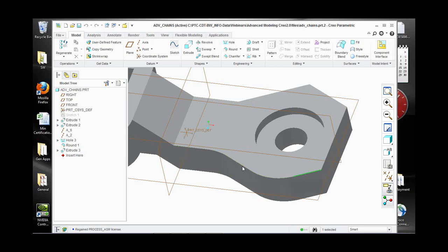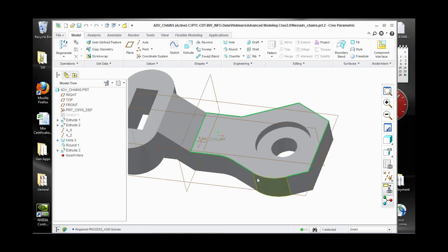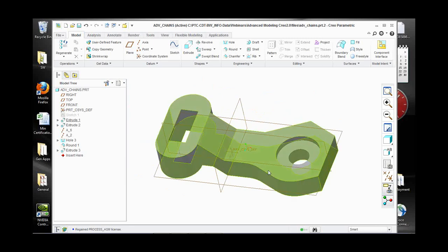other side. So if I hold shift, here's one by one, here's tangent, but if I right click, here's surface loop from one side, surface loop on the other side. If you just hold the shift button when you go over there and then right click quickly, you switch between those two. Pretty straightforward, but if you've never done that, most users will just hold the shift button and pick and pick and pick. Sometimes you make the wrong pick, and so it makes it easy if you hold the shift button and toggle through your right clicks and you get to that same point. So simple things like that, just for surface or for edge selection.